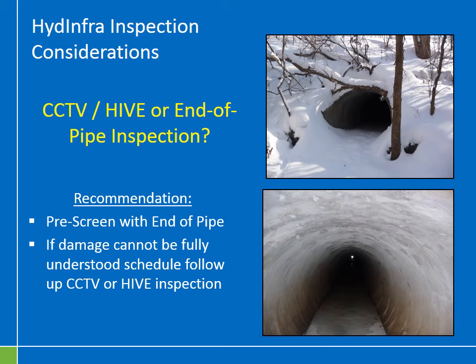So before you go to the expense of mobilizing camera equipment to a site, somebody should go to the site and with a flashlight look in and try to see what they can see. So they might be able to look in there and realize that there needs to be cleaning before the CCTV camera comes out, or they might realize that site access is very difficult. So there's an advantage of having somebody do a little field recon before you get the equipment out there.